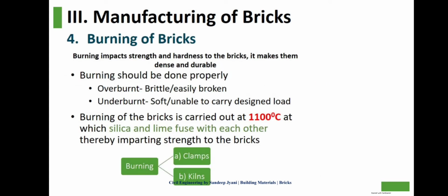Burning of bricks. Fourth, burning imparts strength and hardness to the brick. It makes them dense and durable. Burning should be done properly. Overburnt bricks are brittle and easily broken. Underburnt bricks are soft and unable to carry a designed load.